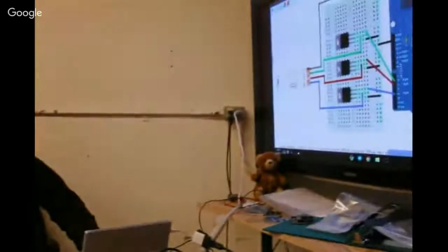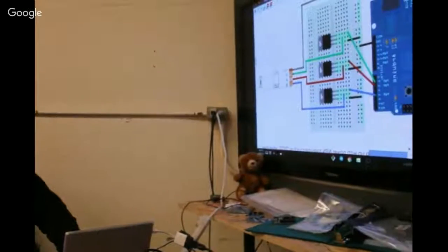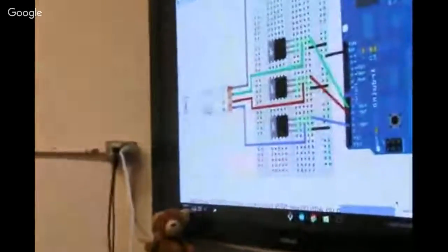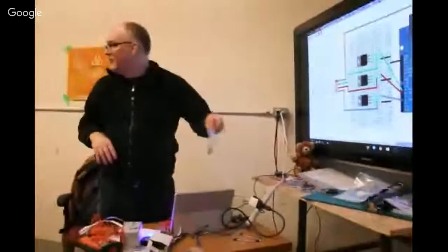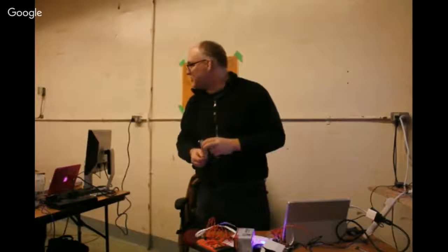So that's a lot easier to see. On the transistors, hold them so that the black part is towards you, and then that'll line up the same way that it does here. We've got this one being powered from the 9-volt on the Arduino. That's not actually what we're going to be doing, because we have a 12-volt requirement on this rather than 9 volts, and we want to be able to use the whole meter of LEDs here to get it bright and as big as possible.